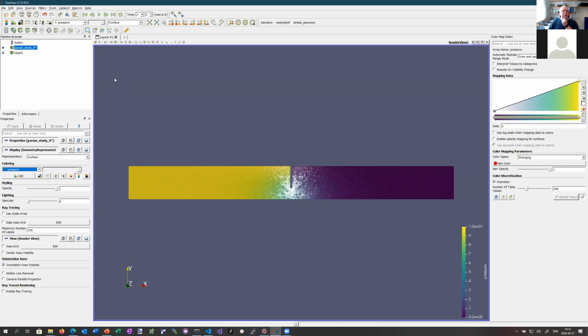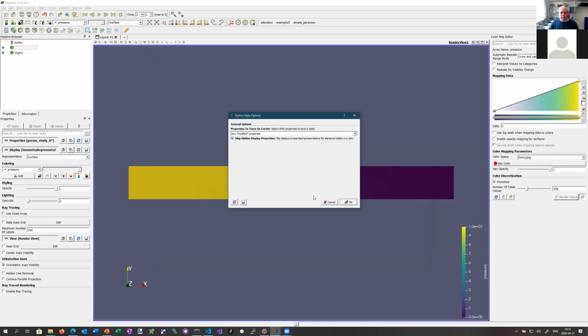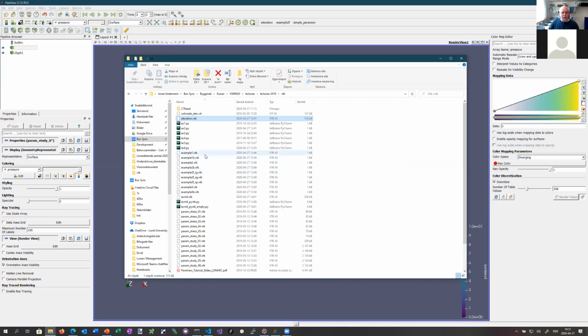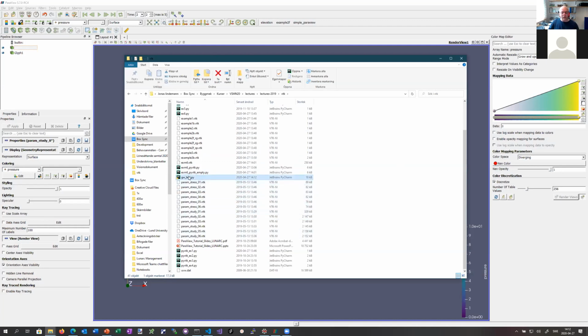What you also can do here, which is kind of cool, is that you can save this visualization as a script. So you can save state, and then you say you want to create a Python state file instead. And then we save it as test. Okay. And then we have GV somewhere here. So it created a Python file here, and if we look into that file,